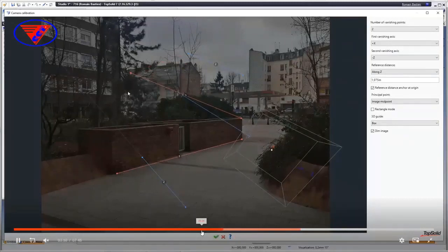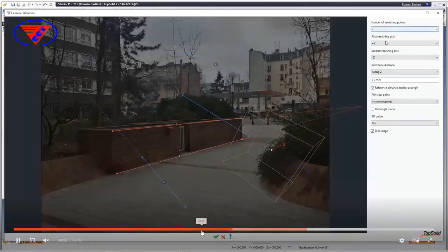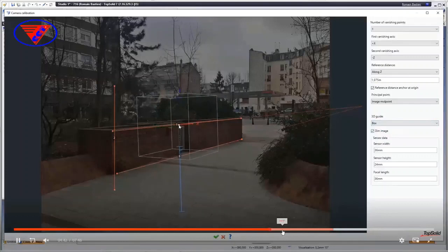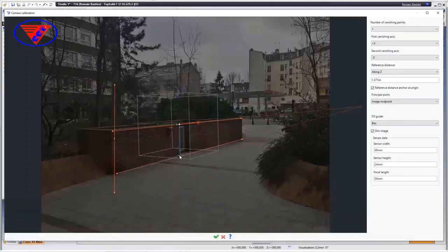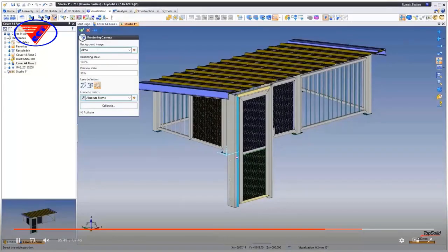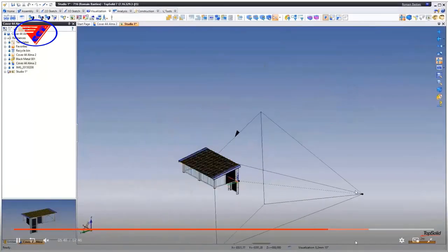We're going to define a second one up at the top. Again, it just helps to align things because this photo has perspective, so we have to take into consideration the perspective. Then we're going to align the next axis, and again, I'll fast forward just a little bit here. Then we're going to set where we want the zero to be. Again, we're keeping in mind that this zero is our zero reference in TopSolid. Then we're setting our scale. So that piece there, that blue piece, is the rise from the floor to the top of that. And then we're going to proceed with the rendering.